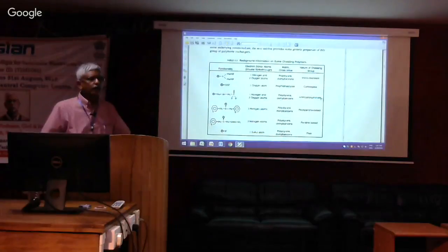Sir, if we regenerate it by swinging the pH, suppose if we use the carboxylate group, COO, it is a weak acid. Yes. So it will work in an environment with higher pH. Yes. During regeneration, if we lower the pH, then obviously it will release. Yes, that's exactly what we do.